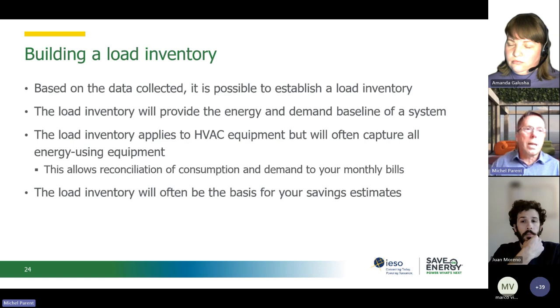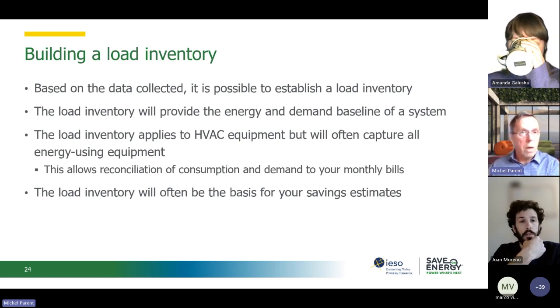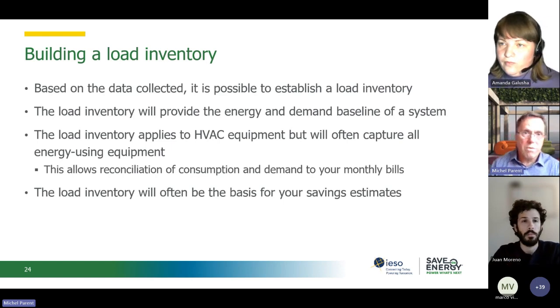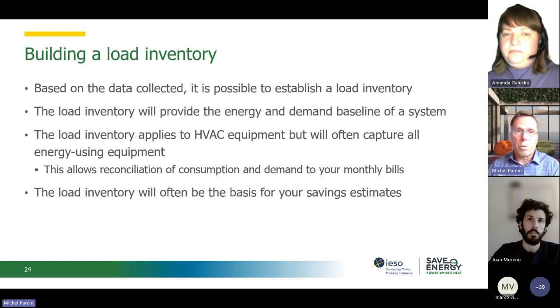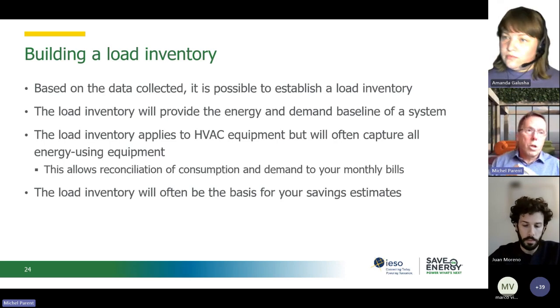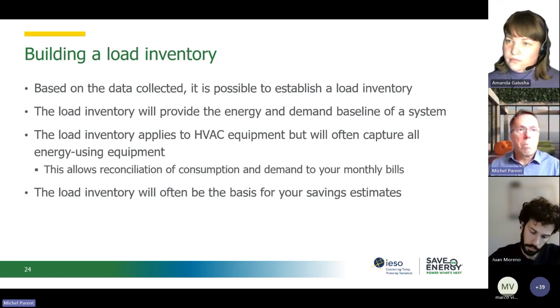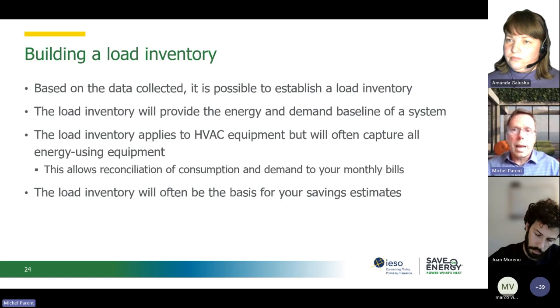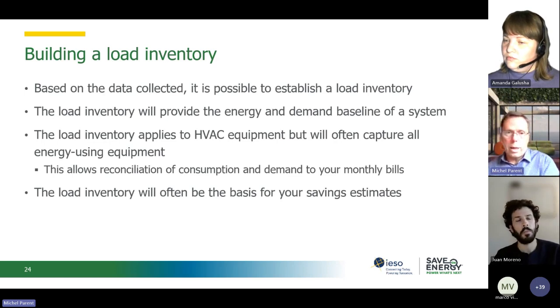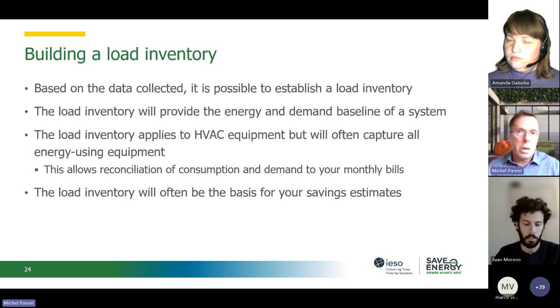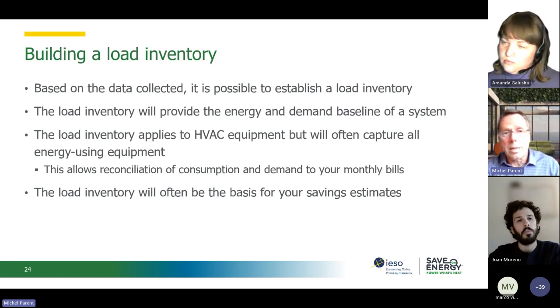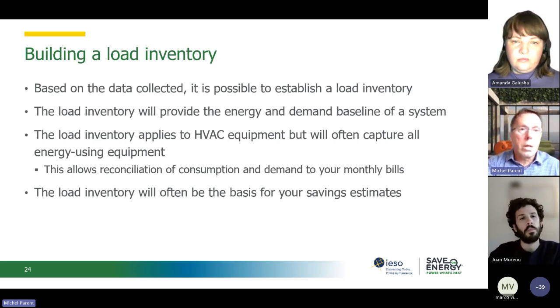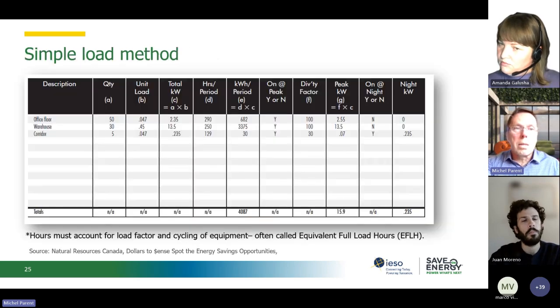And obviously that baseline is typically, unless you do a full-fledged energy model, like I said, and we talked about RETScreen, and I will have a few warnings about HVAC in RETScreen, you have to be very careful, but you will build that load inventory based on what you did. You probably have all that collected in Excel. So very often what we'll do is a thermal balance and an electrical balance. You could also do a cooling balance, where you have, let's say, three tabs in Excel when you do an audit without an energy model to get that baseline information.